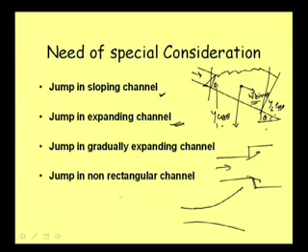Well, sometimes this hydraulic jump can occur in a situation where we are just dropping the channel bed. Suppose the flow is coming and the jump is occurring from this part, and depending on this depth, the jump can occur from this level. So for all those different situations we can have hydraulic jump, and the equation that we are using will not be directly applicable. For those situations, we should go for further study in this topic. It is not very difficult, but we should be aware that the expression will be a little different.